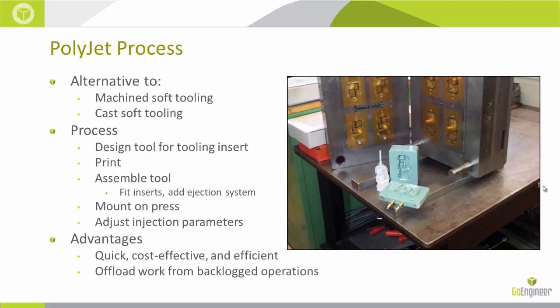Okay. So the advantage here is that it's much quicker. It's much less expensive, especially when you start to consider design iterations. Going back to those tarp clips, I know for a fact that those went through at least 2 to 3 design iterations. And if that step didn't happen, and you went straight to mold tooling, now you're talking about an initial investment in the mold tooling, but also investment into changes. And that's money that's just wasted. It really is. So the advantages here are that it's cost effective and efficient. Again, going from months down to a single day to print these.